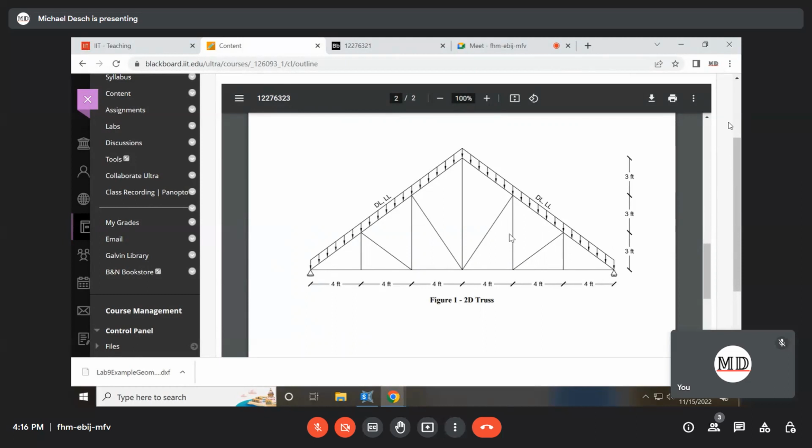So generally what we try and do is we try and find the most optimal for a type of part of our structure here. So like for the bottom chord here, or the top chord here, or for each of our webs here. And what that does is it makes whoever's job who has to actually wind up building this thing a little easier, so they're not trying to play a big steel puzzle that has way too many different parts trying to fit together that are all different shapes and sizes. So make sense to everyone?